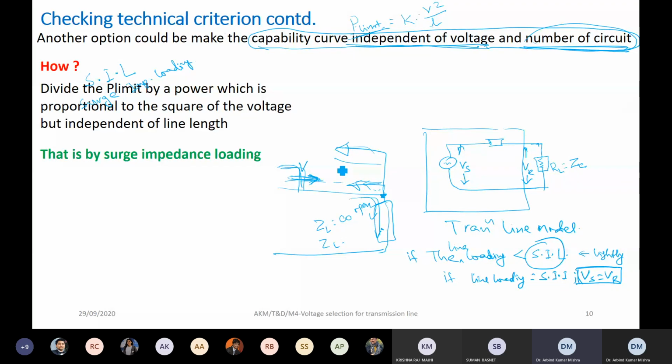So what I mean is, I can calculate, but because of the unavailability of this digital board, I am just explaining orally that if you calculate for a practical line the square root of inductance per unit length by the capacitance per unit length, you will get that this varies in a narrow range around 400. So in the minimum case you may get 380, or in the maximum case you may get 410 or 15 or 20, something like that.